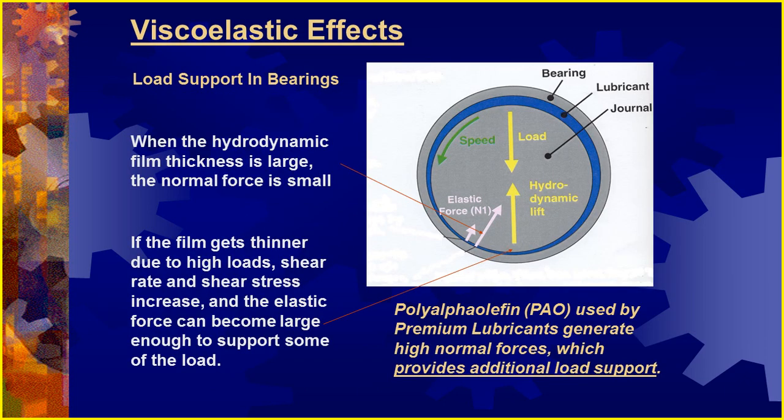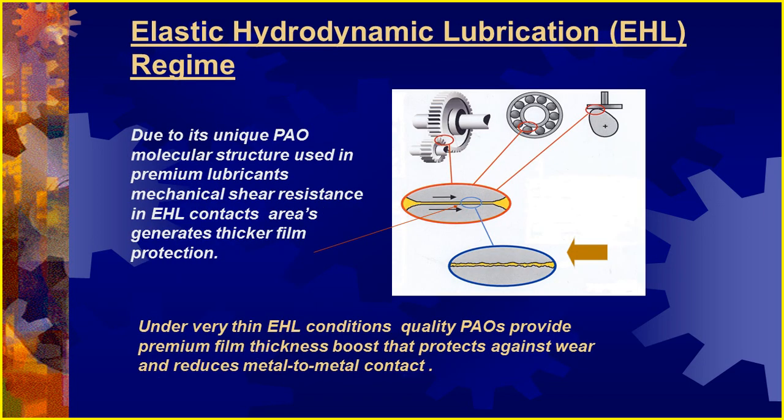We have what's called the effects of hydrodynamics. In other words, where the bearing and the journal work together. We have to be able to look at this and know this, because when you're looking at an oil like a crank on a rod or a rod on a crank in the oil, and how the inner and the outer metal surfaces work, this is also very important for bearings as well. We have the compressibility of the oil. When the oil is hydrodynamic in its lubrication regime, the PAOs, because of the consistency of the molecules, can have greater stability in the squeezability or the hydrodynamic lubrication requirement.